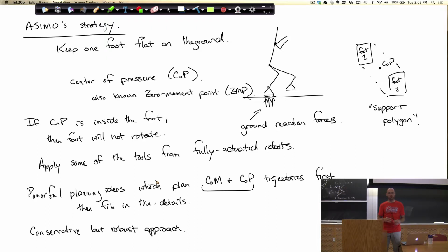A lot of times you put a load cell in the hand to estimate some carrying load. You don't have to have a perfect model of the object you're manipulating, for instance. If you just know its contribution to your hand, you can factor that into the contribution of the whole mass. And in practice, these guys do walk around. A lot of them use just the center of the hip as a surrogate for the center of mass, and that's a robust enough idea that the estimate doesn't have to be perfect.